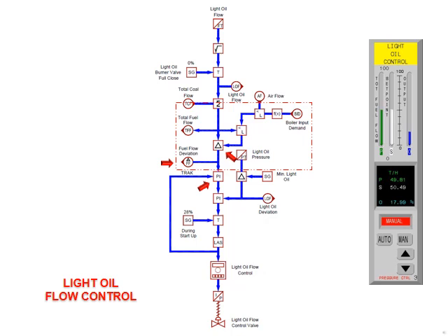This creates an error signal, or fuel flow deviation, which is processed through the proportional integral block to the light oil flow control valve. The light oil pressure is also compared to the minimum pressure, which is 15 kilograms per centimeter squared. If it is below the minimum, an error signal is processed through the controller. During startup, the controller contains a 28% input signal. Startup is defined as less than 2 oil burners in service.